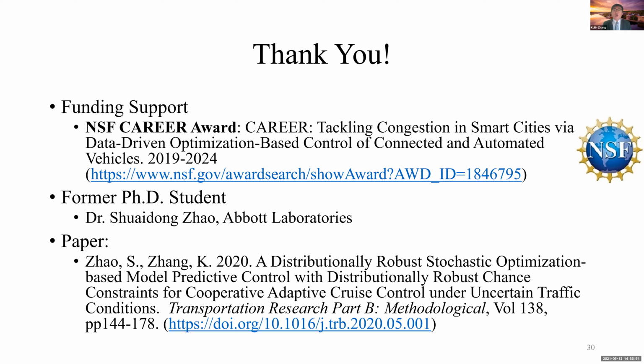And another thing: why we still use the MPC model for this is because our decision variable is continuous, because acceleration is our continuous variable. From my understanding, reinforcement learning may be good when the decision is a discrete state, which is faster. If you look at the continuous one, then you will have the curse of dimensionality problem, basically. So we didn't use that one, but we use this one. But that's something we need to consider. Yeah, that's a very good question.